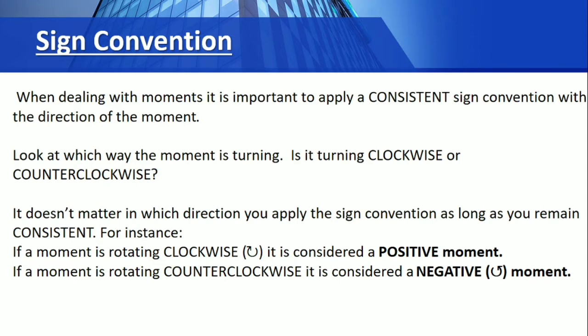So para maging consistent tayo, when dealing with moments, it is important to apply a consistent sign convention of the direction of the moment. So dalawa lang naman yung direction natin, so counterclockwise or clockwise. So always remember, clockwise is positive and counterclockwise is negative.